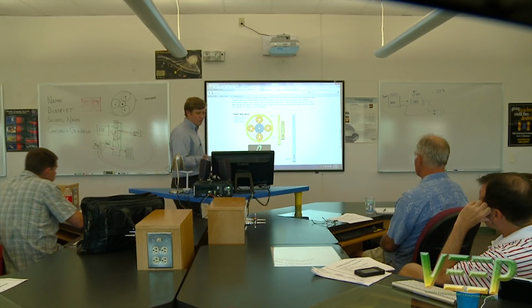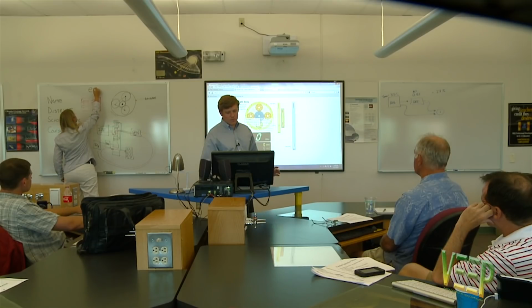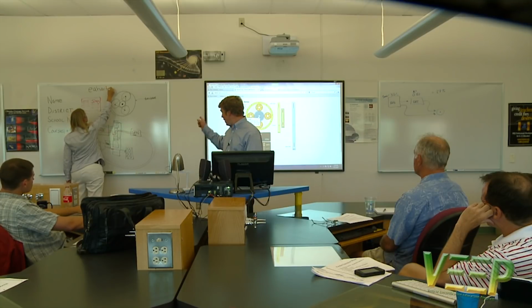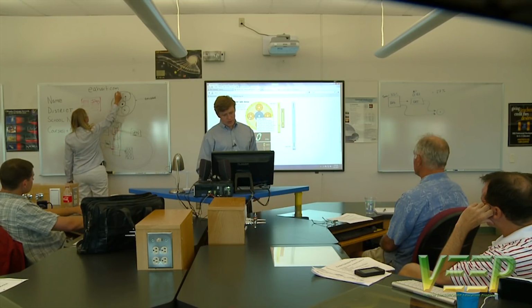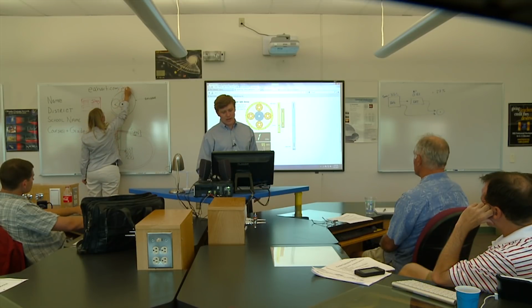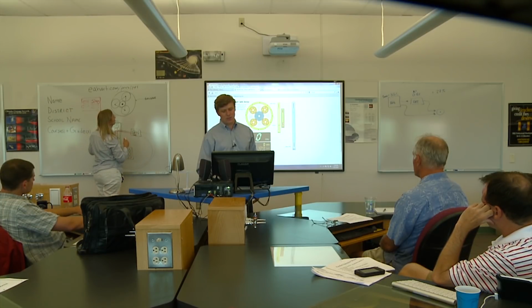So let's try something kind of fun. Let's idle the car, okay? Let's watch how the Prius idles. Here's all the pieces again. The sun gear is connected to MG1, which is the generator. MG2 is on the output, and the engine is on the planet carrier. The global idea is that we have to set 2 of these, and then we get the third. So for instance, if I set MG2 at 0 and I set the internal combustion engine at idle, 1,000 RPM, then that tells me how fast the generator has to spin.